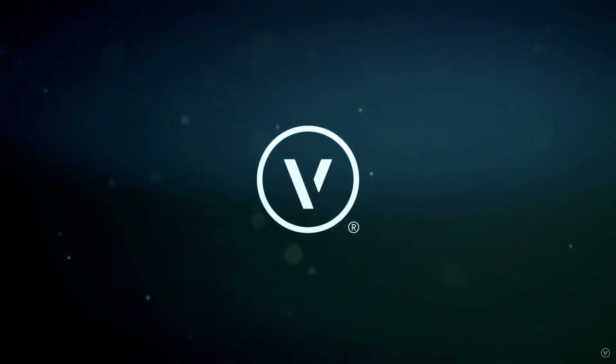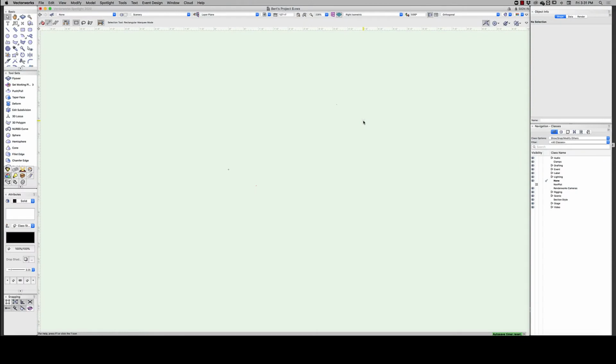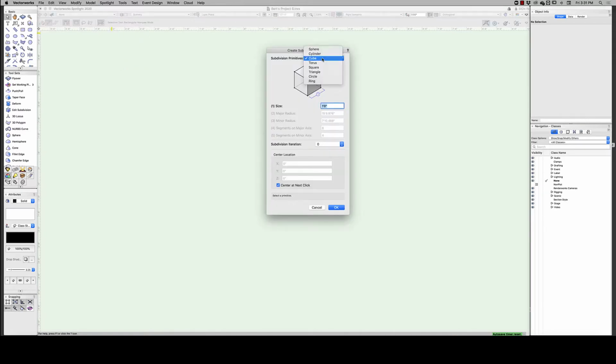So that's the project, and we'll get started. We'll start in a new Vectorworks file by going to Model and creating a subdivision primitive. We're going to create a cube that is 12 inches or 1 foot square with the iteration set to 0. So cube, 12 inches, 0.